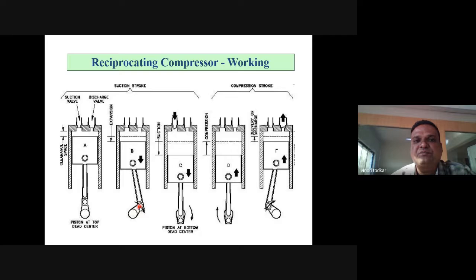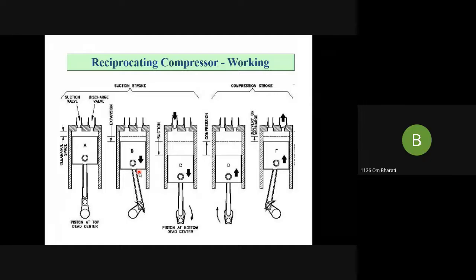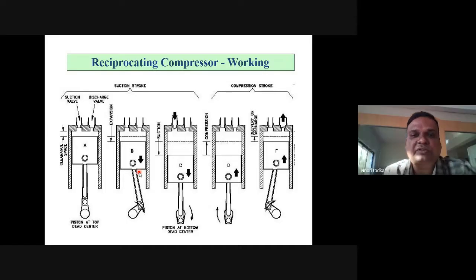The crankshaft will rotate. Now see, when your crankshaft rotates, your crank will rotate because your crank is mounted on the crankshaft. So initially, when your crank moves from this vertical position to this downward position, what will happen? Let's say now the crank is at this position and it has started moving in the clockwise fashion. So tell me, when the crank moves in the clockwise manner, what will happen to the piston? Piston goes down. Excellent.